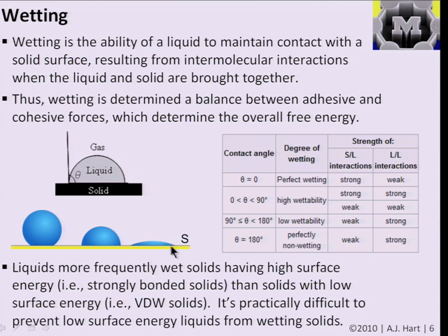by a liquid like so, which is quantitatively referred to as having a small contact angle, because classically the contact angle theta is measured through the fluid from the substrate up to the edge of the meniscus here, or to engineer surfaces so the liquids don't like them, or they don't like the liquids. And that is the case where you have a large contact angle, and there's a large angle if you measure through the fluid like so.